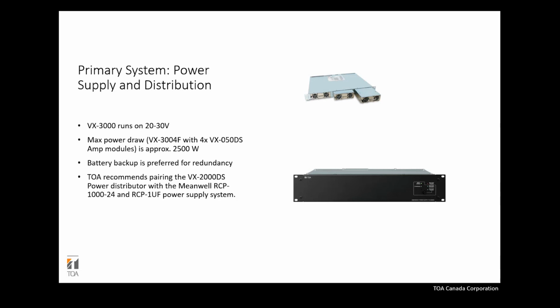We designed this like that because we noticed that in the case where there's a short circuit on one of the channels, that avoids failure cascading throughout the device. So not all channels are affected, only that one channel is shut down, and there's fuse protection for it so that the power supply is protected.